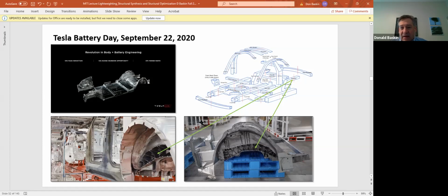So by combining lots and lots of parts into a single casting, you can not only reduce the amount of money you're spending in some cases, but also you can reduce weight very, very substantially. The strategy to make big castings has been around for at least 20 years that I know of. There was some work back at Chrysler in the early 2000s with Alcoa. And there have been some big castings from Ferrari and more recently the new Corvette and Audi A8. But it is picking up.